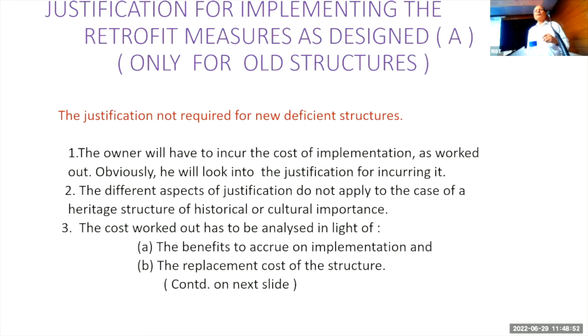So here in retrofit measures, we go for item rate basis. For each item, we have to prepare a list of items which are involved in the implementation of my retrofit measures. So there to work out the cost, what basis I will consider? There, after seeing the list of items of works involved, I have to identify what are the items which are included in my standard schedule of rates. So for each location, say for Assam, if I go for designing a retrofit measures, I'll have to consult the SOR for Assam, given by Assam PWD, like that for other places.